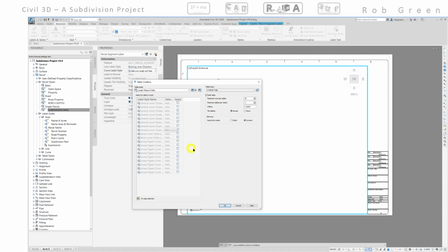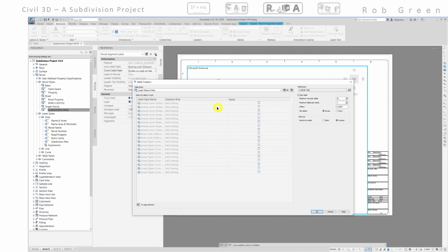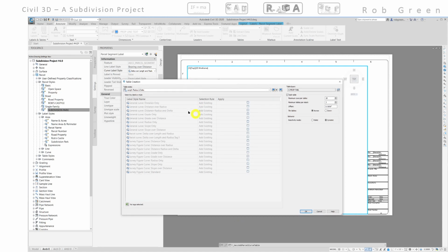So quite honestly, a really common technique of mine is as soon as a dialog box opens up, especially in Civil 3D, the further we get, is to drag that dialog box way out and look at a column, and if I can't see all the data, I'm going to drag that column out till I see all my data. Civil 3D is really good at bringing up a dialog box in a way that very specifically does not show the information it needs to show to effectively use the dialog box. It's just one of the drawbacks that the user interface has. And if you get in the habit of immediately sizing a dialog box so that you can see everything, you're going to find that these dialog boxes are pretty powerful.